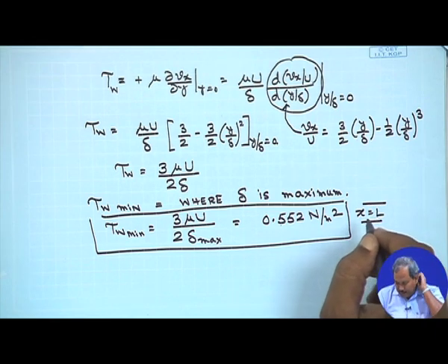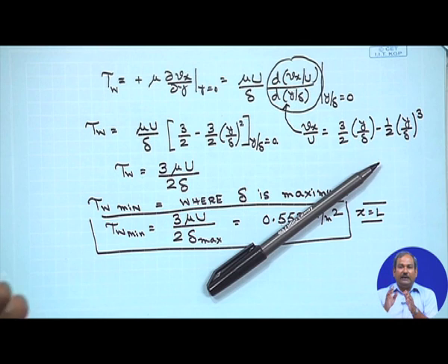So at the edge of the boundary layer, at the end of the plate, the location at the end of the plate would provide you with the maximum value of the boundary layer thickness, and also at this point you would get the least value of wall shear stress. So wall shear stress is a monotonically decreasing function of distance, and delta is a monotonically increasing function of x.